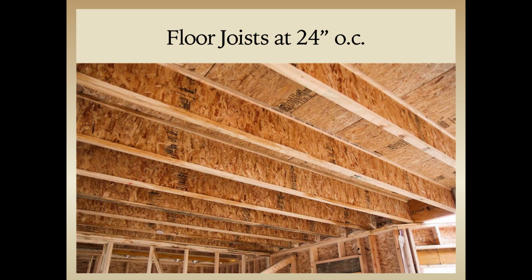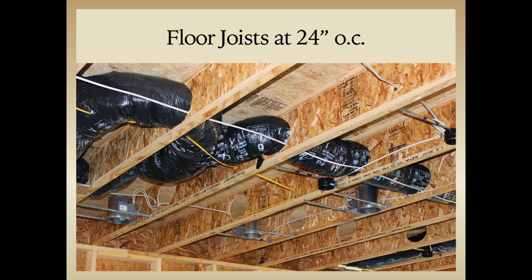When using stacked framing, your floor joists are also going to be placed at 24 inches on center. This detail has both advantages and challenges. So first, the advantages. The wider joist spacing provides big cavities for HVAC and other equipment to be run. The switch to wider joist spacing typically also requires a switch to a deeper I-joist, which will allow for larger holes in the web. These larger cavities and bigger web holes simplify the process for the HVAC contractors on site.